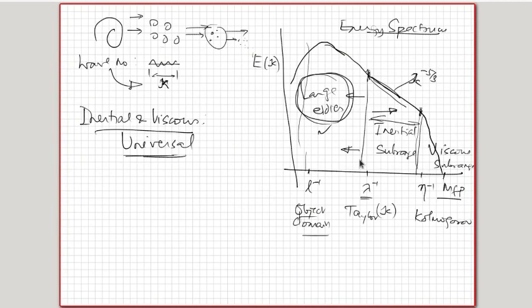So then what this says is that from the Taylor microscale upwards is what you need to actually calculate using CFD, and what is on this side can be modeled reasonably accurately, because the model is going to be the same whether it's a flat plate boundary layer, a flow past a sphere or cylinder, a flow past an aircraft, a flow past a blade, or a flow inside a pipe. Whatever is the flow, the mechanism for this side is going to be the same, so you can make measurements in simpler geometries and simpler cases and prepare the model and use it for complex cases.